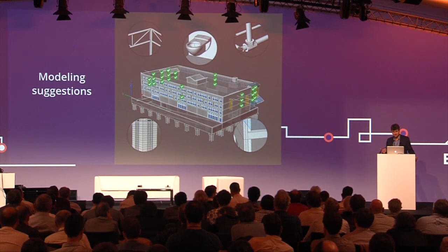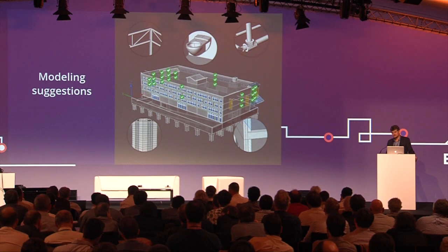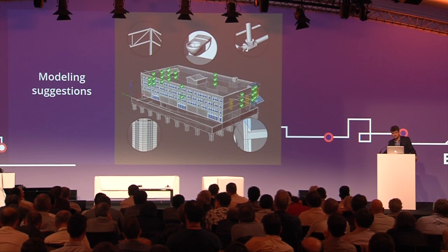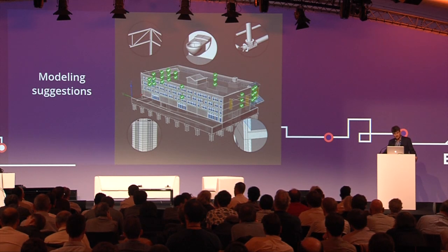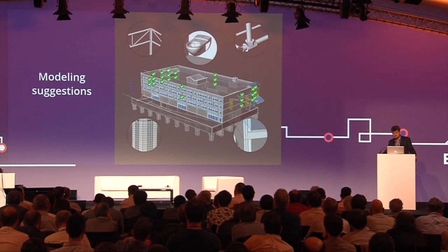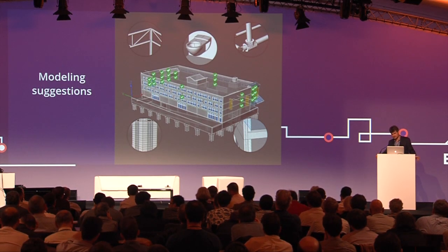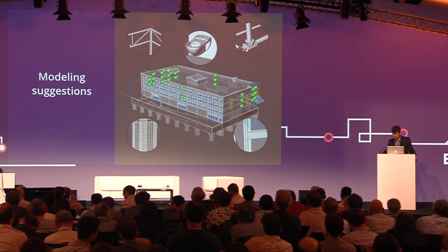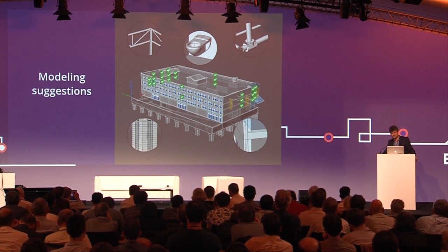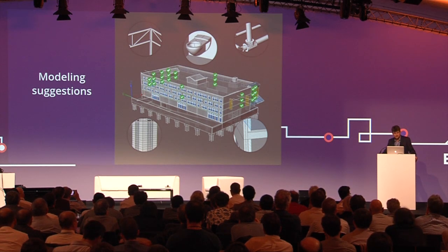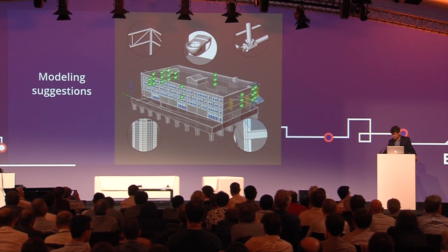This idea is very simple, and in V18 we released it for connections between architectural elements, but we don't have to stop there. We can use the same approach to also handle connections between structural and MEP, and between the various aspects. We can also use it to place flow terminals or to place windows or create patterns of windows. We can even use it to assign compositions.